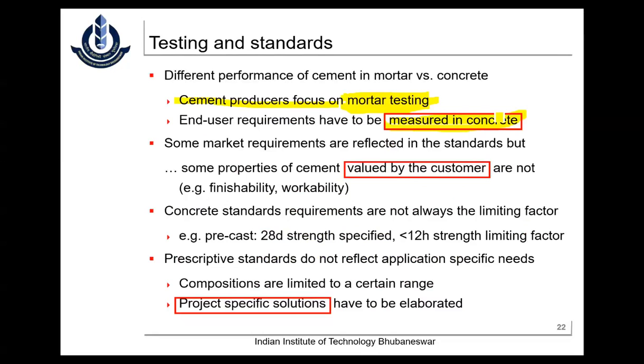Between infrastructure projects, as a consultant, I tell them, even a small contractor, please have a small concrete lab. Have one quality engineer and some basic equipment. Periodically you check the quality of the cement in the concrete, so there should not be any variation. The quality engineer does all this work, so that you will not end up with any problems. This will not cost much also.